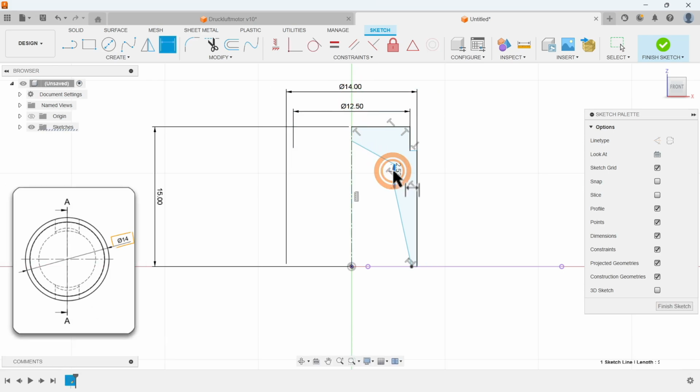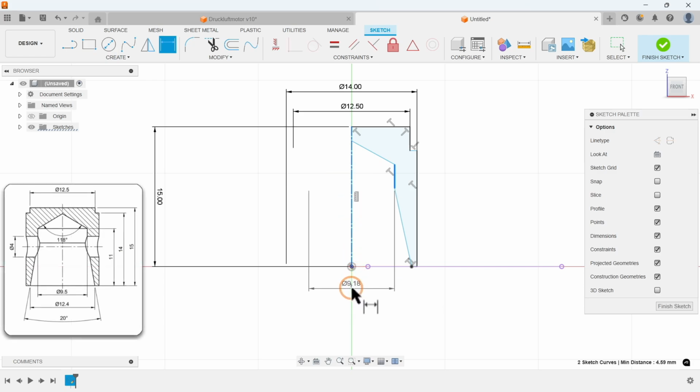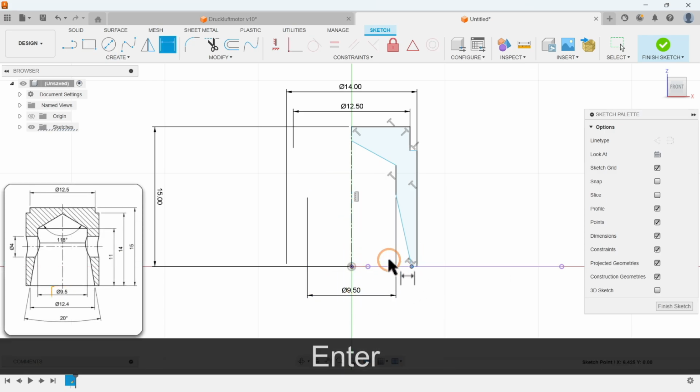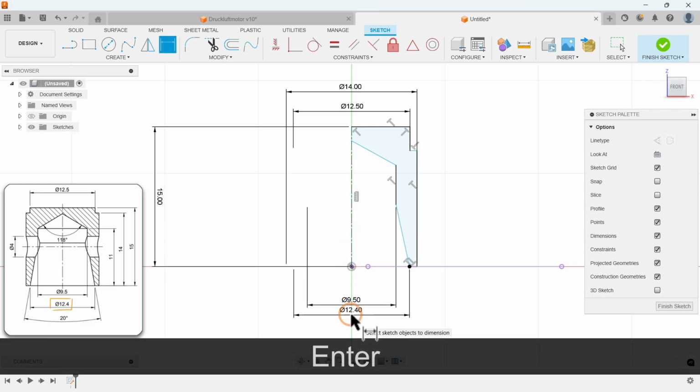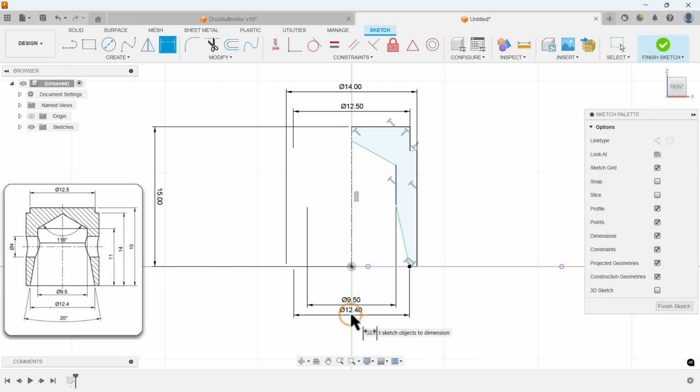It is important that the sketch is fully defined in the end, so that you have complete control over the component. As an additional aid, you could also load the component drawing into the program, allowing you to easily trace the contour, as with the crank pin.